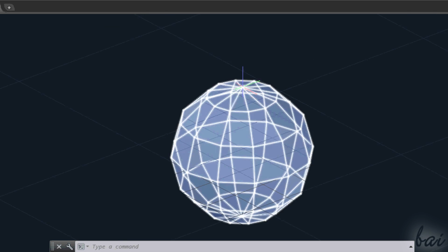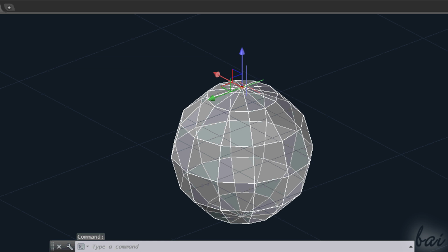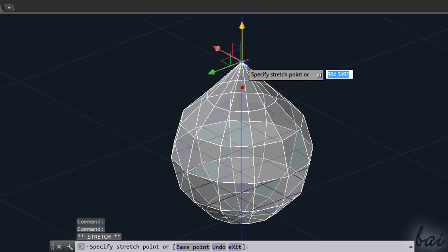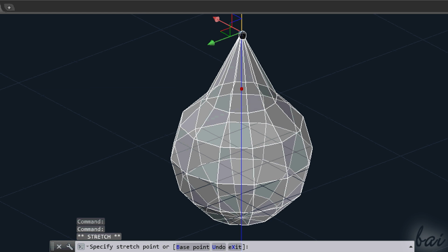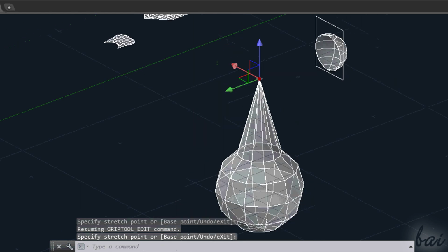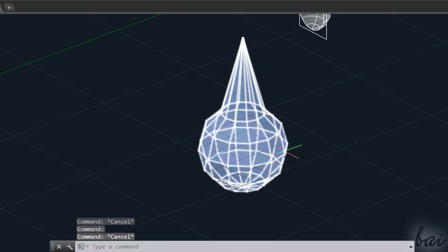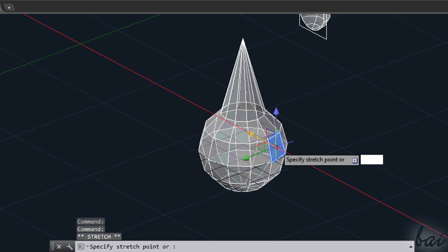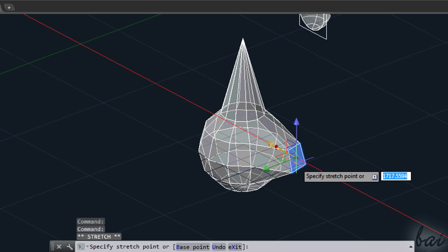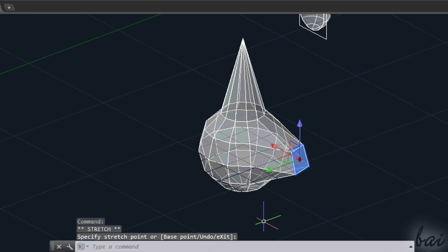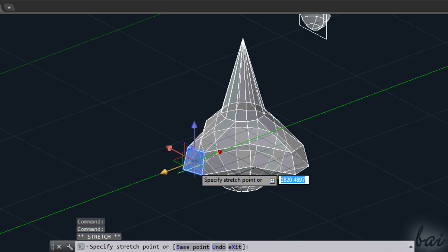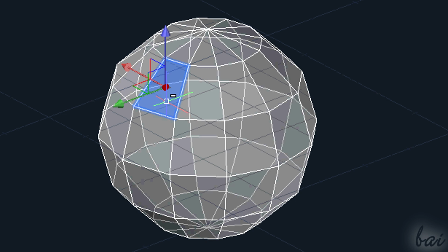The principle of these mesh objects is to draw a 3D personalized solid faster and easier. You always start with an object that is not smooth at all. You can select any face, node or edge to move them using the system that appears. Depending on how you move these, the shape of the mesh does change. Faces selected show a red point on them, edges a red rectangle, and vertices a red point.